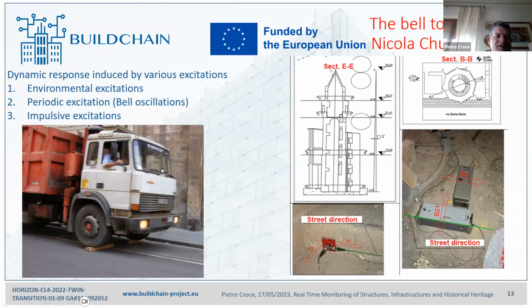The problem is that in this case, due to the particular geometry and the particular situation of the bell tower, we discovered that this specific excitation is not able to excite all the relevant mode shapes, due to the difficulty of transferring the vibration to the structure.